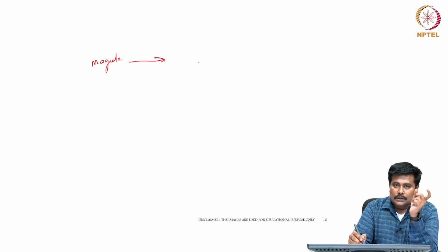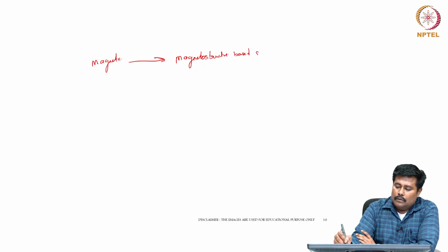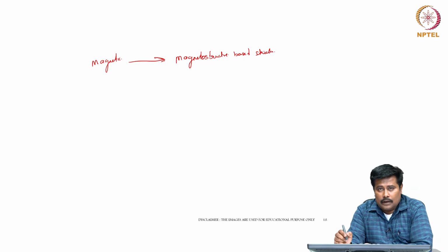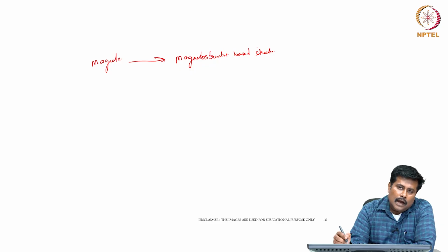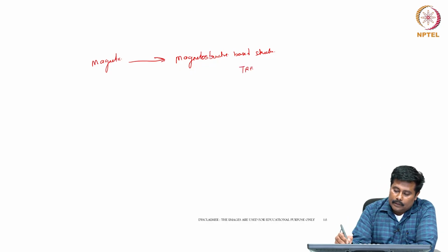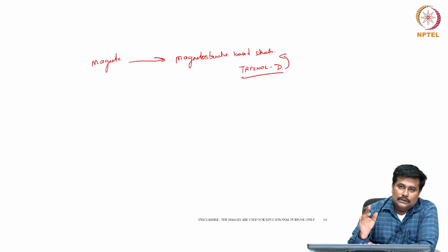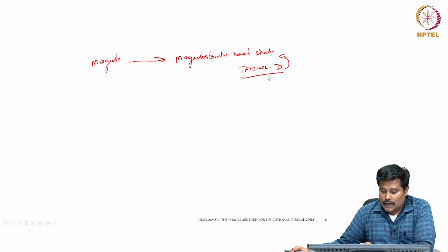In addition to this, there is one more concept which is available, which is also called magnetostrictive based structures. These magnetostrictive based structures are not efficiently used for micro robotic applications. However, there are wide varieties of applications with reference to different devices. Terfenol-D is considered to be a standard material which is used for such kind of magnetostrictive structures and applications.